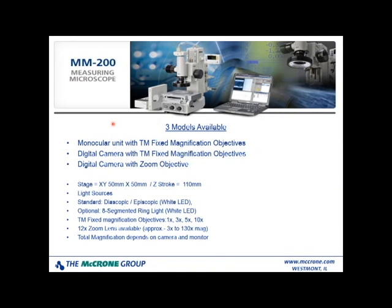There are 3 different varieties of measuring microscopes. This is the smallest one, the MM200. It can be configured in 3 different ways. One with either a monocular eyepiece tube, which we saw originally, or you can have 2 versions with a camera only and no eyepiece. One with a fixed magnification objective and one with a zoom objective. The MM200s come standard with a 2x2 stage, 50 millimeters by 50 millimeters travel.